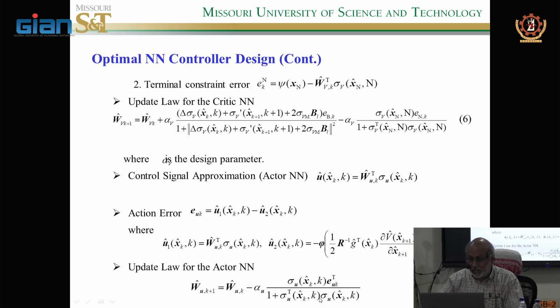So you're using everything, observer state, also the input error. Input error also uses the observer state. And it also uses the non-quadratic phi. You see the phi there? The phi was not there before. The phi is coming here because of the actuator saturation, to accommodate the actuator. So it truncates the value of the command input that goes into the actuator. You see that phi, and you select that phi.